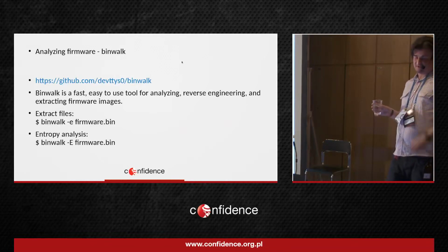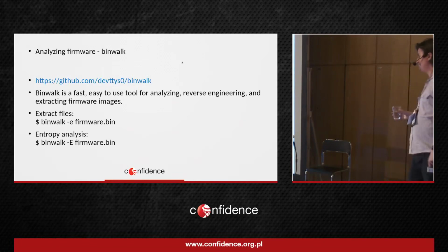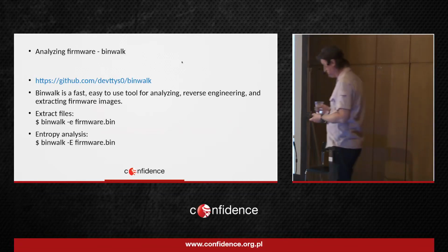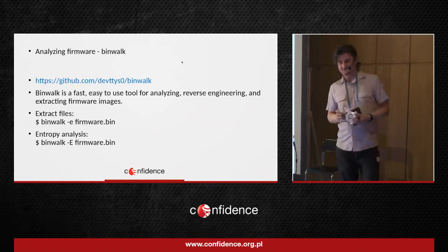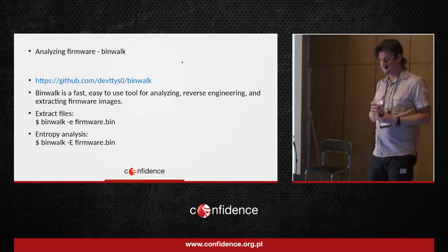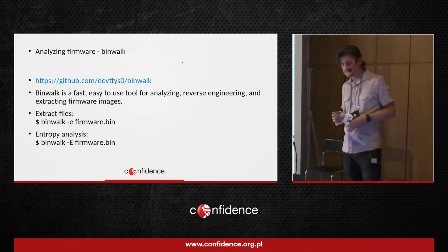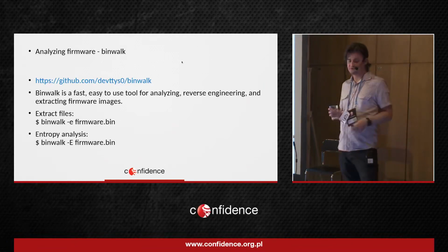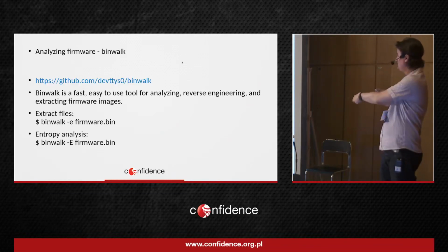So, when you have a firmware, we want to analyze it because we need to split it into parts. There is a very nice tool called binwalk. This is binary walker. It is a program that tries to find signatures of the bootloader, kernel, root file system, and other stuff in the image, and tries to extract them into files. So this command will extract everything that it finds.